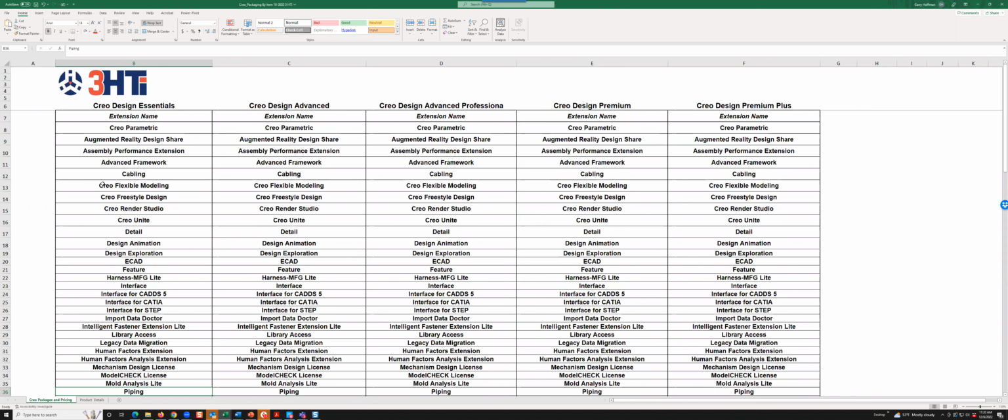So flexible modeling, and I mentioned the Co-Create stuff that came into this. Ultimately, Creo, like Pro Engineer, is feature-based solid modeling, where you have parent-child relationships, features are intelligent, they go in a certain order, and what came before affects what came after.